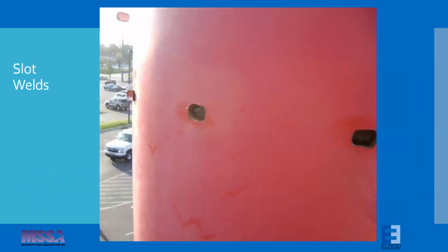In this photograph of slot welds, you can see that the inner compression ring from this upper pole stage is not connected to the lower pole pipe stage at all. You've just got those slots. The slots are there, but there's no weld. And because there's no weld, that inner pipe is not connected to the outer pipe. So the stresses that come from the upper stage of the sign are not being transferred efficiently to the lower pipe. And by not transferring efficiently, that means you're creating added stress at other locations, which is giving a higher chance of failure of the sign structure.